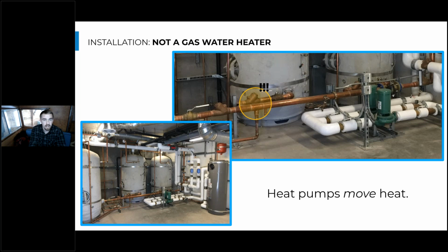And one example I've seen here with Colmac heat pumps is they often pair the cold water line going to the heat pump together with the domestic cold water line going into the tank. So this line has the potential to bring in cold water when there's building usage, but the heat pump also uses this line to pull cold water out of the tank.